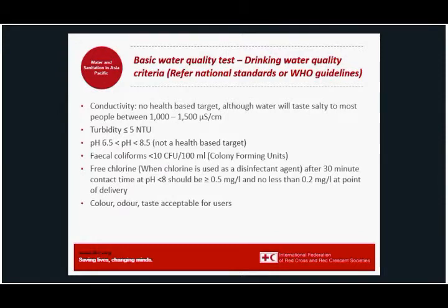So before we go any further, it'll be useful to define a few of the water quality parameters that we are commonly discussing when it comes to water treatment. First one is conductivity, which is a measure of how salty the water is. And this can be a particular issue in regions that are close to the ocean. Most of our standard water treatment equipment does not deal with salinity sources. So salinity or conductivity should be checked to see if they meet the requirements.